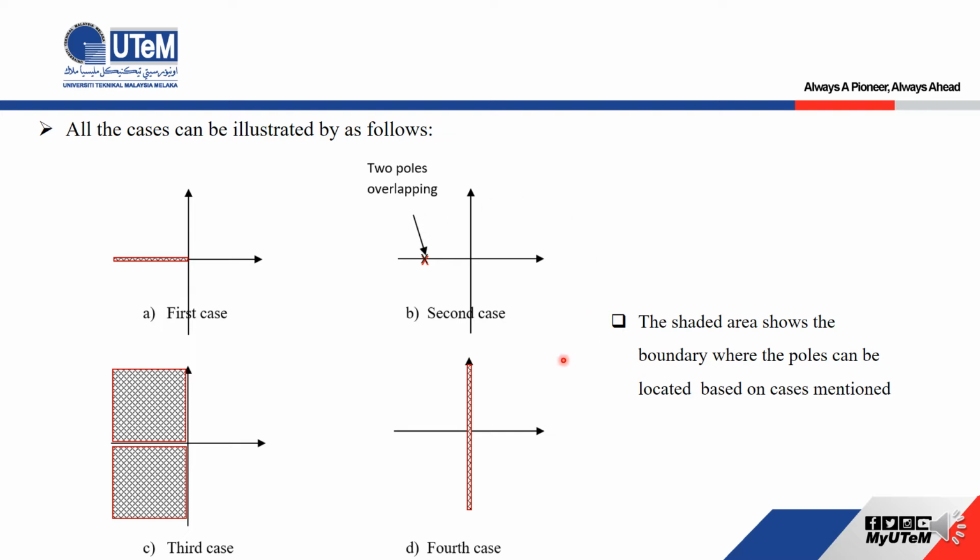For the second case, the system is in the critically damped condition. Both closed-loop poles for critical damping are at the same location like this, overlapping one another. The poles are only located at one position and only involve a fixed gain value. That means the parameters such as settling time and rise time are fixed for the critically damped case.